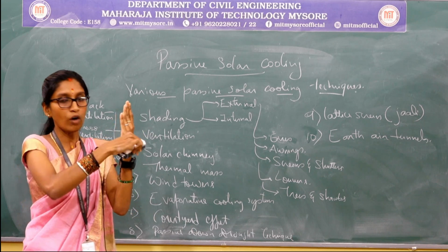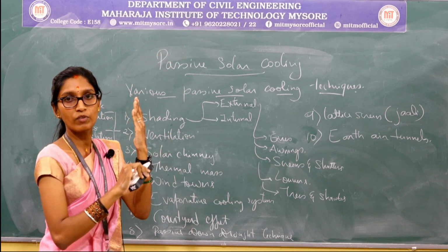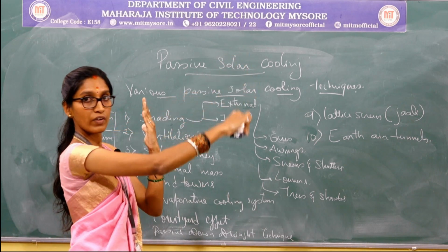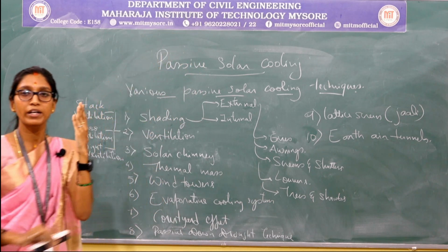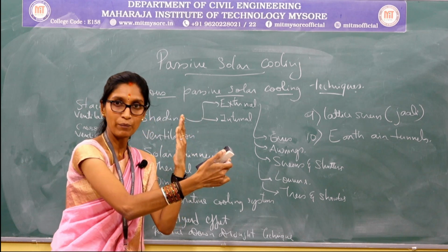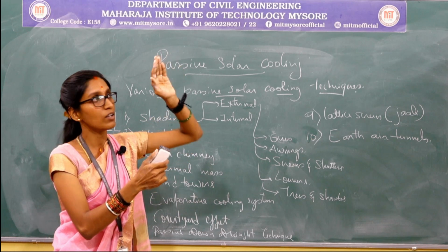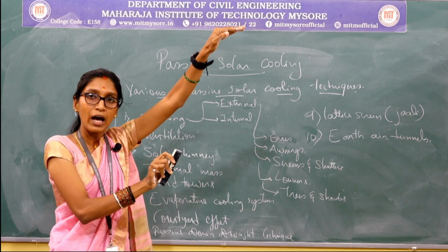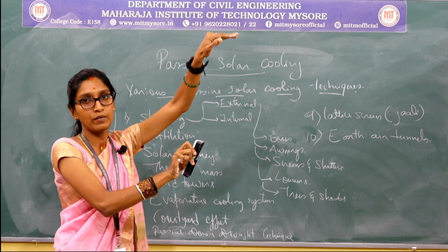So what to do? Obviously the hot air which enters the building should move out through some way. So south facing walls have an opening, and say in the north facing walls I have provided the openings at the top. The ventilators are provided at the top. So the air which gets into the building from this end, being lighter, will rise up and move in the upward direction, and good fresh air has a way to get into the building again, right?